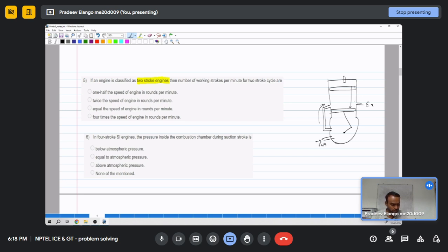The hot gas will start exiting through the exhaust port, and then once it uncovers this intake port, it will start compressing. Till then it will be only a gas exchange process, and then while it moves up, in the first few crank angles it will be in the gas exchange portion, and then it will start compressing, and similarly while expanding till this point it will be the power stroke, and then it will start with the gas exchange.